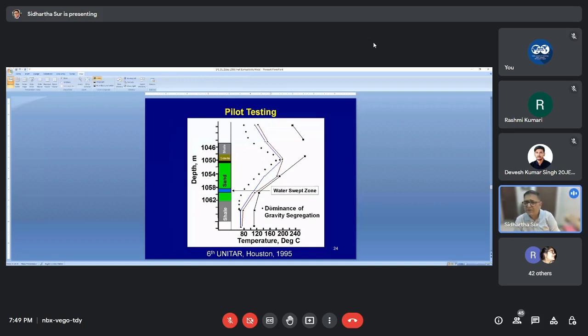And one beautiful thing is that you can see the blue path when that injector well was drilled, maybe a month before, 2 months before the process start. The aquifer water encroachment zone was indicated by reduced oil saturation area. But when the process started, air injection started, we were apprehensive that the front can go through the high permeability zone of that less oil saturated blue area.